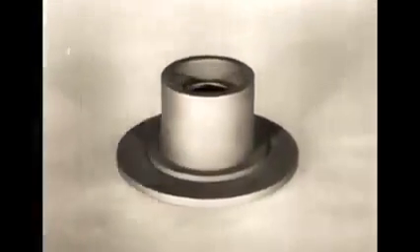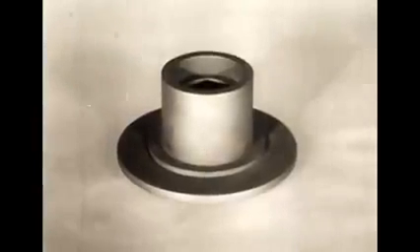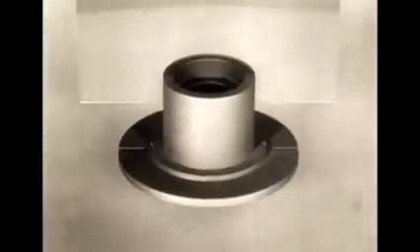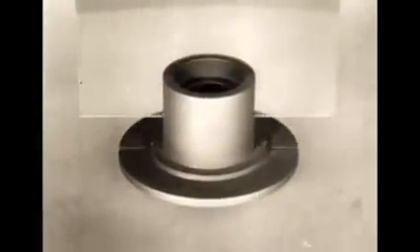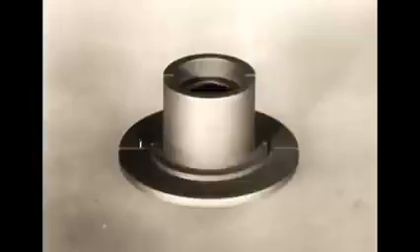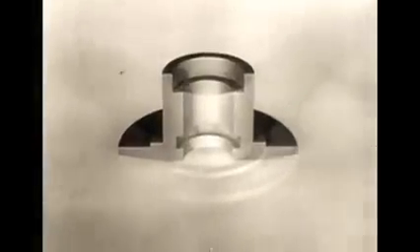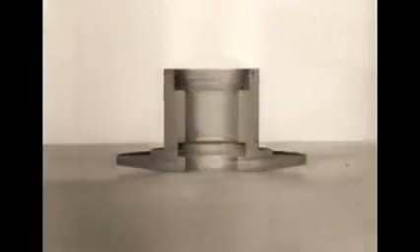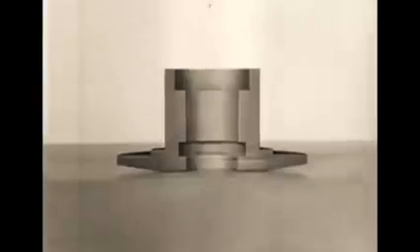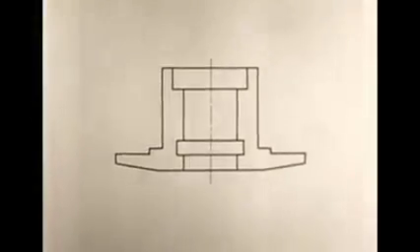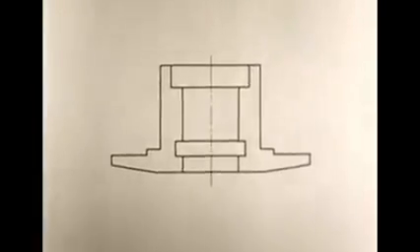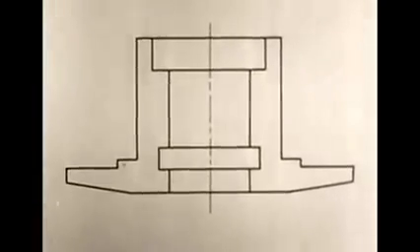You can make your drawing easier to read by a method called sectioning. Imagine that you can pass a cutting plane through the object, and that the part of the object in front of the plane can be removed. Now you can see all the inside details clearly, and you can make a drawing of the hub as usual in orthographic projection. This view is called a section or sectional view.